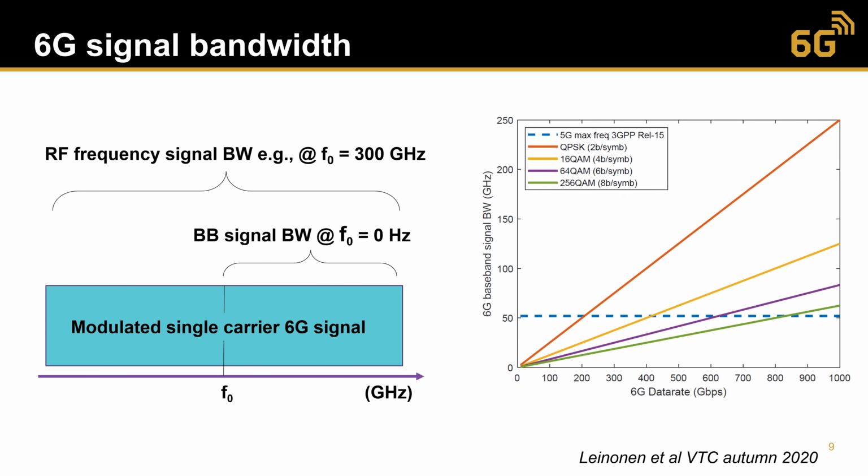The extreme 6G data rate systems require substantial frequency support from the radio solution. It has been envisioned that a 6G system could support even 1 terabit per second data rates. The RF bandwidth of the signal is dictated by the used modulation, or how many bits per hertz it can transmit. Analog baseband bandwidth is half of the RF signal bandwidth if IQ receivers are used.